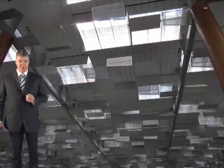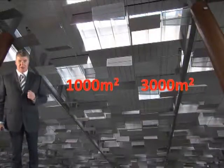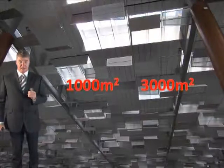Now, the first thing to determine is the number of reservoirs that you're going to have. So that's the first thing you should do when you decide on natural or mechanical: how many reservoirs are you going to have. Now, for cost reasons, again, normally people try to have the minimum number of reservoirs that you can. So you don't want loads of reservoirs, you try and get the minimum you can as long as it achieves the design objectives. Now, there are limits to the maximum size you can have for a reservoir. Well, generally, smoke reservoirs are limited to between 1,000 and 3,000 square metres, depending on the circumstances. And this is to ensure that there is no significant loss of heat. In other words, the smoke will be extracted.